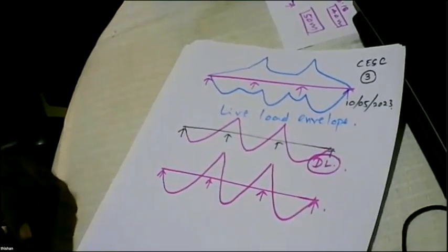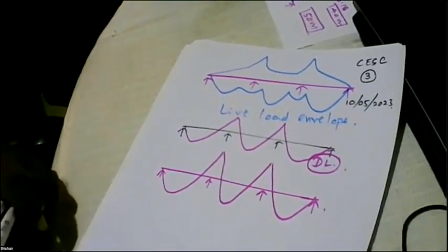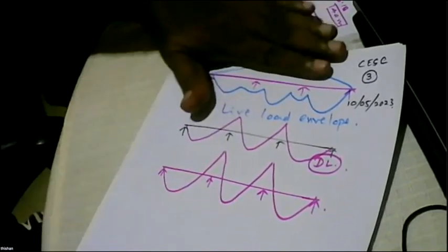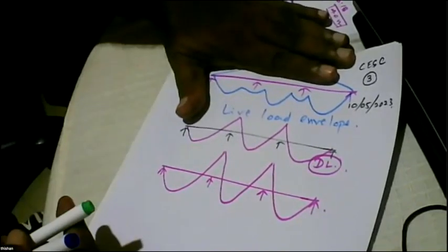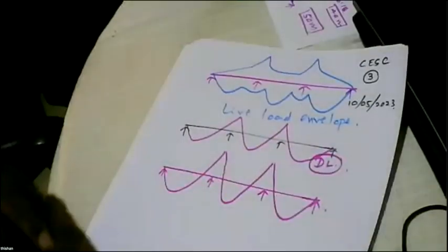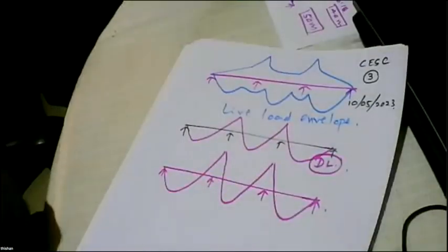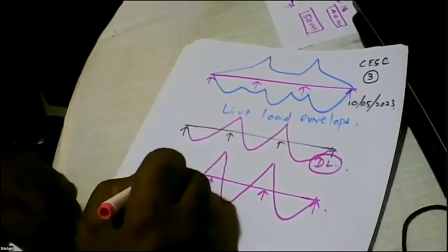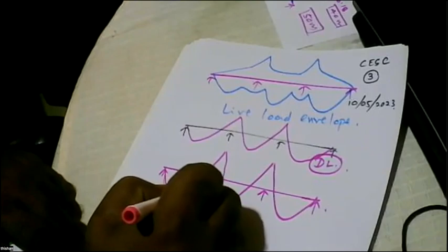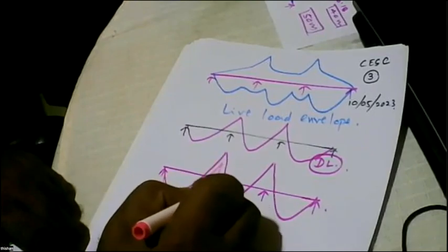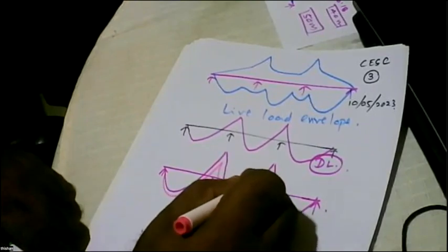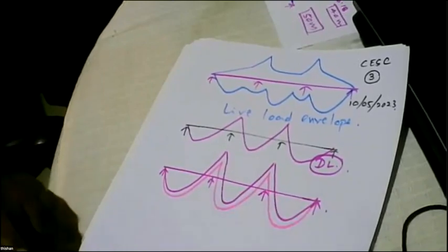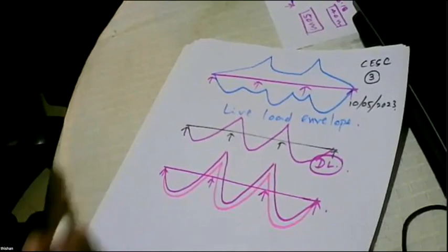Now we are going to look at the live load. Now what will happen? Generally, if you have only this part, what is visible, then the bending moment will be on the lower side. But now what we have is not one pattern, you have a system. So which means the bending moment diagram will go like this. And on the other side, it will go like this.